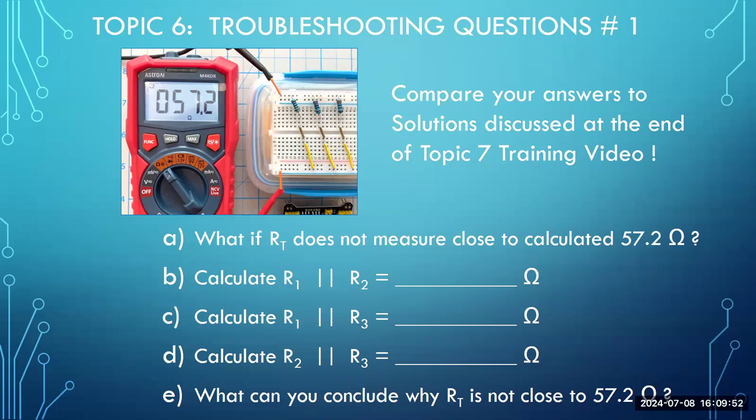But here's the challenge, the troubleshooting. Suppose, I mean, in an ideal world, the calculated value is 57.2 ohms, and your R total measures 57.2 ohms like mine does, but suppose it doesn't. What if your R total on the measurement is not even close to the calculated 57.2 ohms?